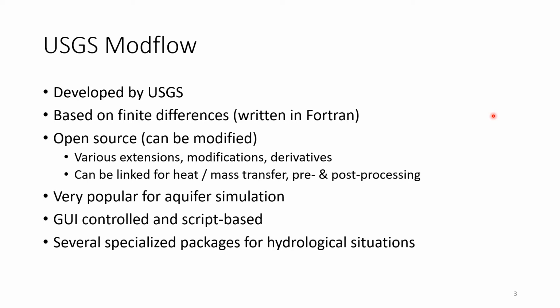It is based on finite differences, quite unique this time, as all the more modern software will be based on finite elements. The neat thing here is it is open source. So in principle, you can modify the code, and there are various extensions, modifications, and derivatives of USGS MODFLOW, which sometimes makes it a bit difficult to find the right version for you.